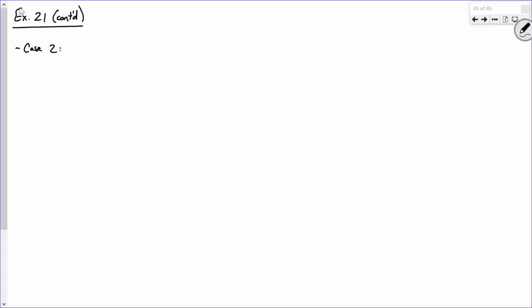Now, case 2 has a maximum live load deflection of what? L over 500. All right. So it would be wonderful if I could just use the beam that I used previously. Okay, it'd be great. The problem is that I don't know if it's going to meet deflection requirements. Now, there's an easy way of going about that, and that's doing a little bit of algebra.